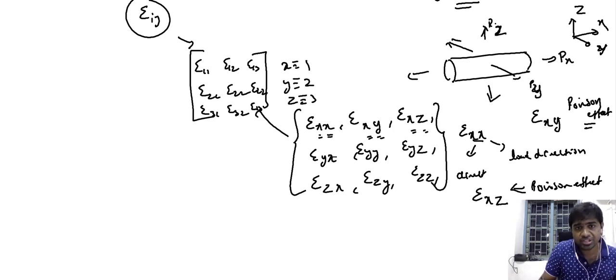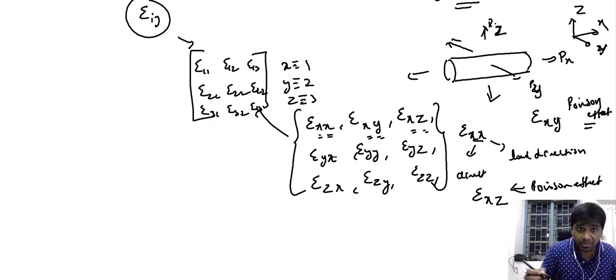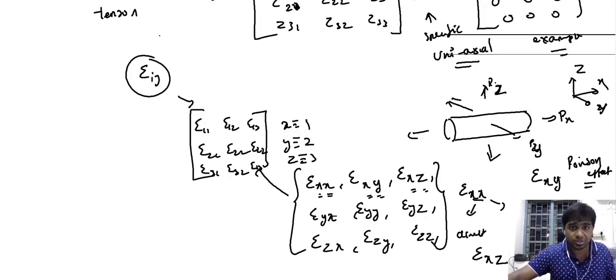So what we have essentially done is represent the different values the strain can assume, depending on the indices, in the form of a matrix. This matrix representation means we have included all the possible values and represented them in a unique way, such that the order of the indices also has a significance. So the generalized representation of the strain, similar to that of the stress, requires more than a vector.